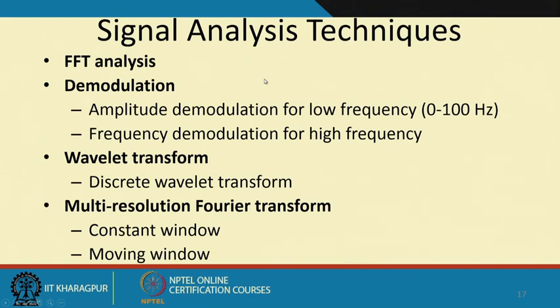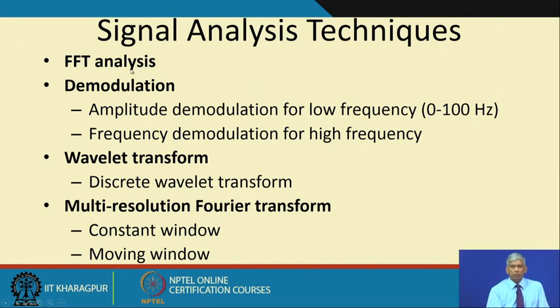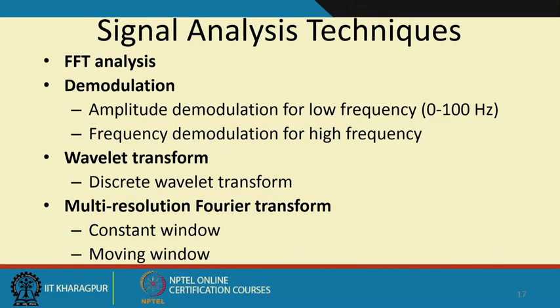So, once this signal has been acquired from the DAQ system into my computer, I need to do some sort of an analysis. The conventional FFT analysis sometimes becomes problematic because of the low signal to noise ratio, and then we may not be able to capture these signals. But if we demodulate the signals, we can very easily calculate and identify the defect frequencies, and if there are transients, as if the gearbox or the mechanical unit is not running at constant speed, we could use some of the non-stationary signal analysis techniques as well.